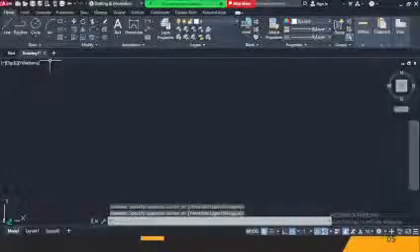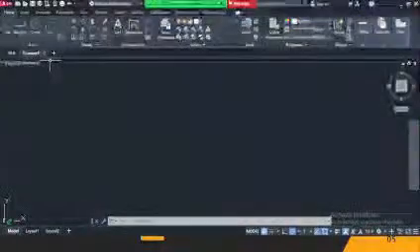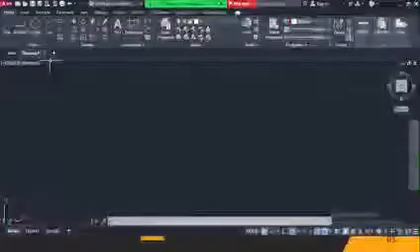The major difference between the two is that when using the blue marquee selection tool, you need to select the entire object that you want to pick, but while using the green, you don't need to select the whole object. All you need to do is select one part of the object and everything is selected.